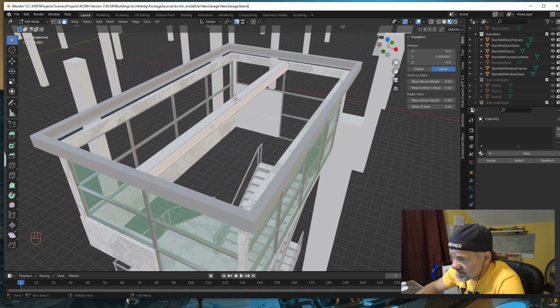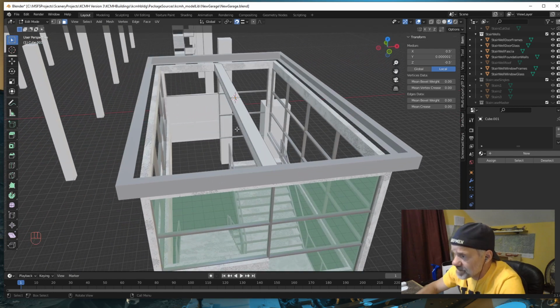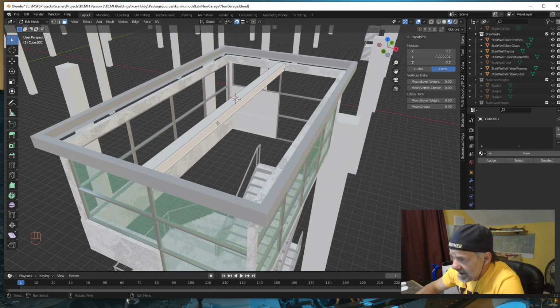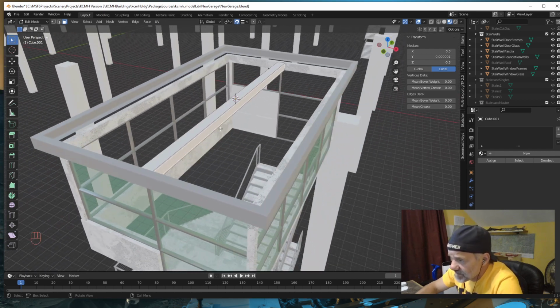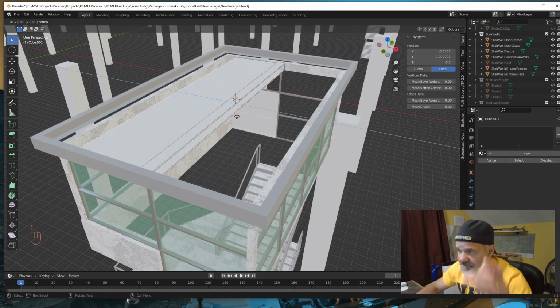So I'm just going to select this face. Oh, I'm sorry, but both this face and this face were selected. All right, but I'm going to just do this side first. I'm going to select that face, and I'm going to extrude it in the negative direction.